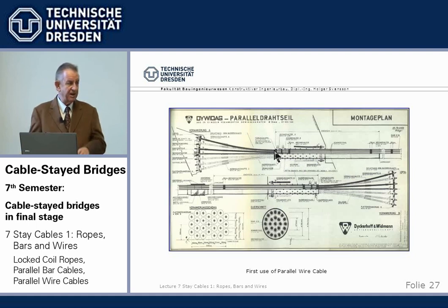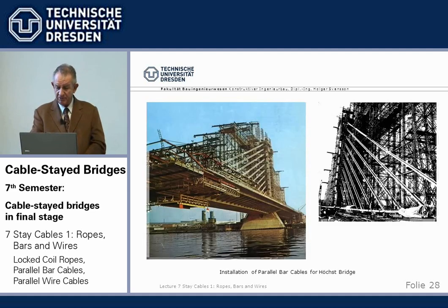So the basic idea was that permanent loads are taken by the stress bars, and live loads, the fatigue range, are mainly taken by the steel pipe. So he tried to distinguish both loadings to the 2 parts, bars and steel pipe. Very ingenious, it worked, all the tests were done. First example, as I say, Höchst bridge.